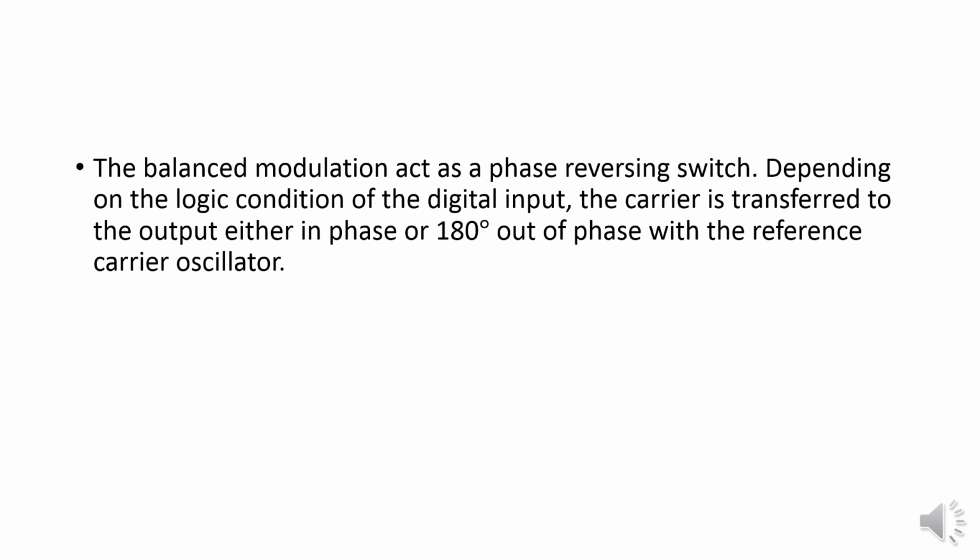Here the balanced modulator acts as a phase reversing switch. Depending on the logic condition of the digital input, the carrier is transferred to the output either in phase or 180 degrees out of phase with the reference carrier oscillator.